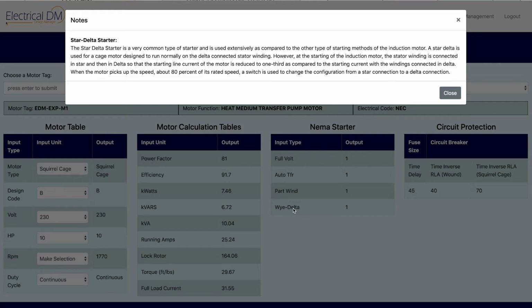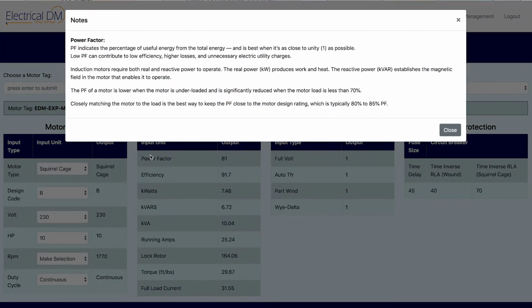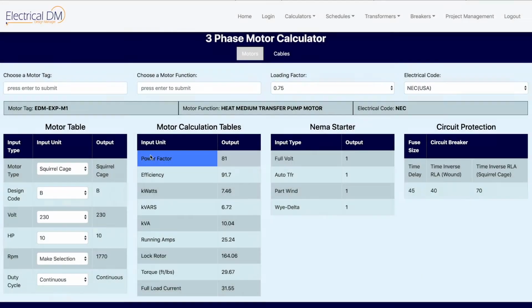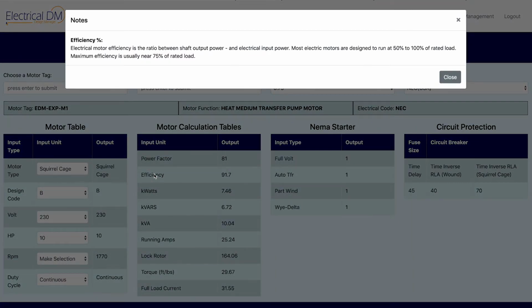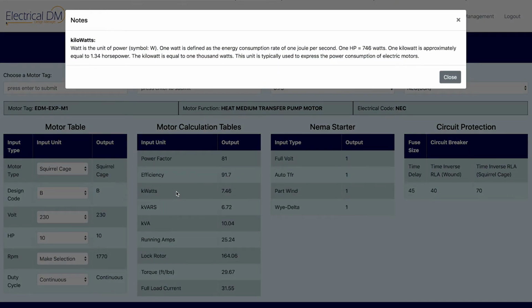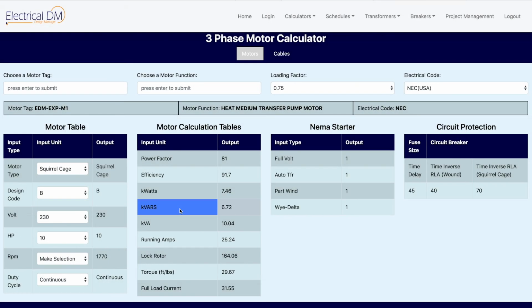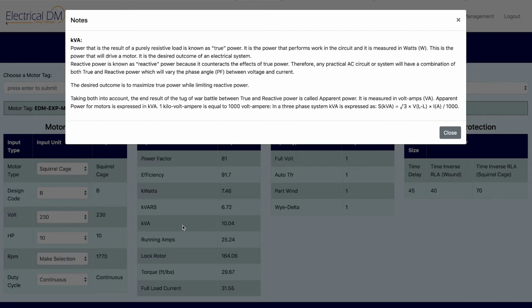However, the full load amp designation is determined when the motor is tested after manufacturing is complete. Each motor will have a unique FLA rating depending on the manufacturer, materials, etc. Once determined, this value is then added to the nameplate. EDM's goal is to bring the design stage of the motor calculations as close as possible to the manufacturer's FLA nameplate rating. Also, each motor has a service factor designation, ranging from 1.15 to 1.25, depending on the manufacturer's design.